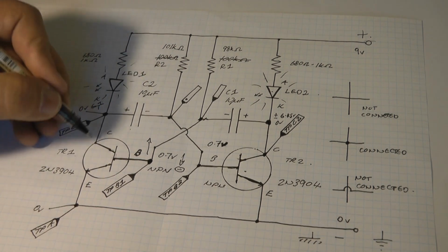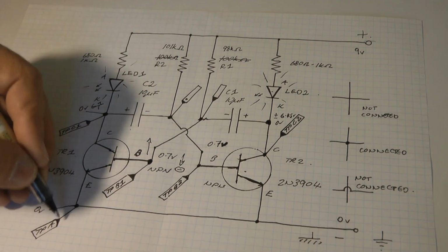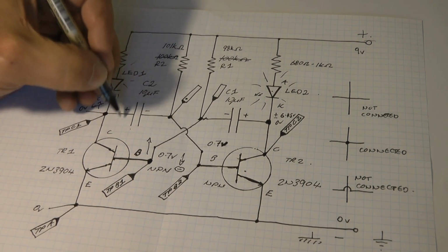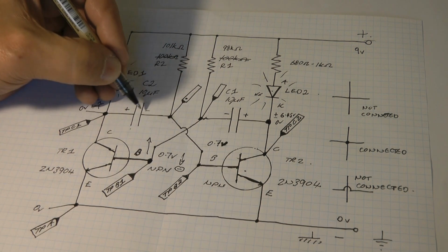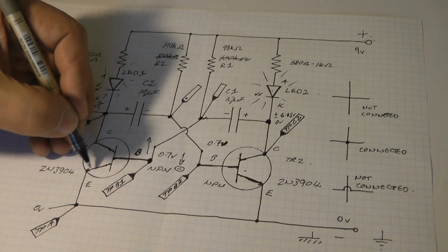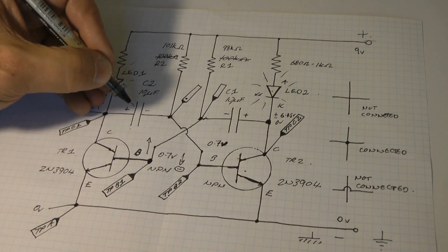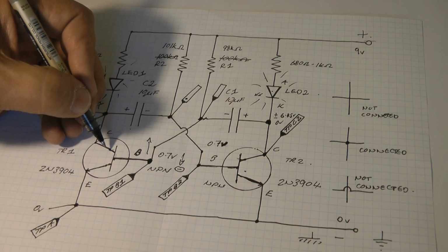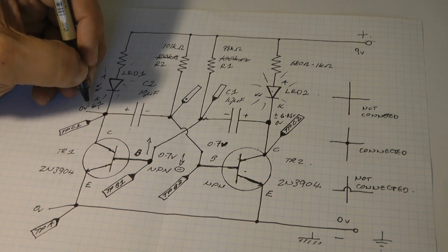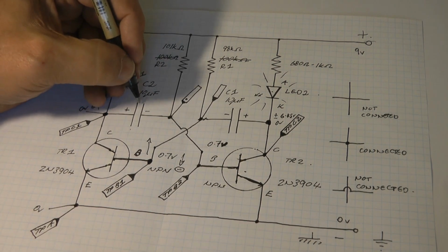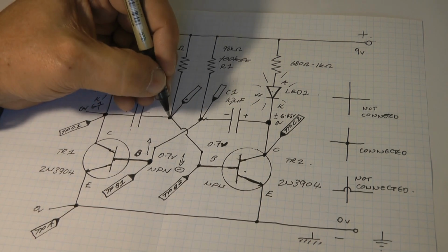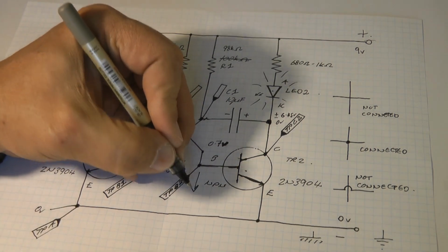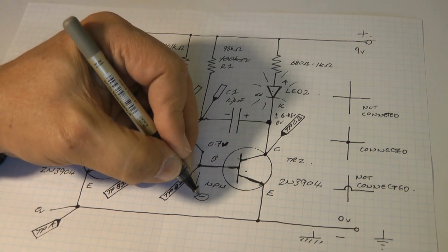So this transistor is now on and it's conducting. That point is 0 volts. In the meanwhile, this capacitor would have charged up, so it had a voltage across the plates. But as this switch closed contacts, this capacitor can't discharge as quickly as the contacts on the transistor closed. So you've got 0 volts here, which forces the voltage across this capacitor to drop at this point, which is connected to that point, into deeply negative territory.